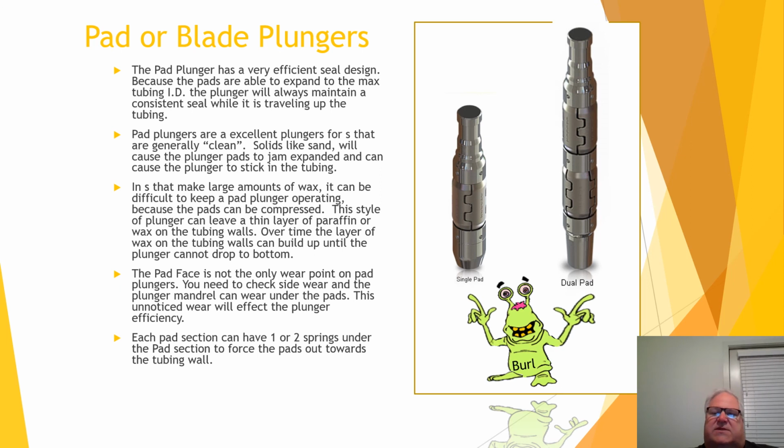So the only time I would recommend these plungers is in a nice clean well, which can be nice clean oil or nice clean water, no sand, very, very tiny amounts of paraffin if any at all, and if you've got a weak well where you need that really high efficiency.